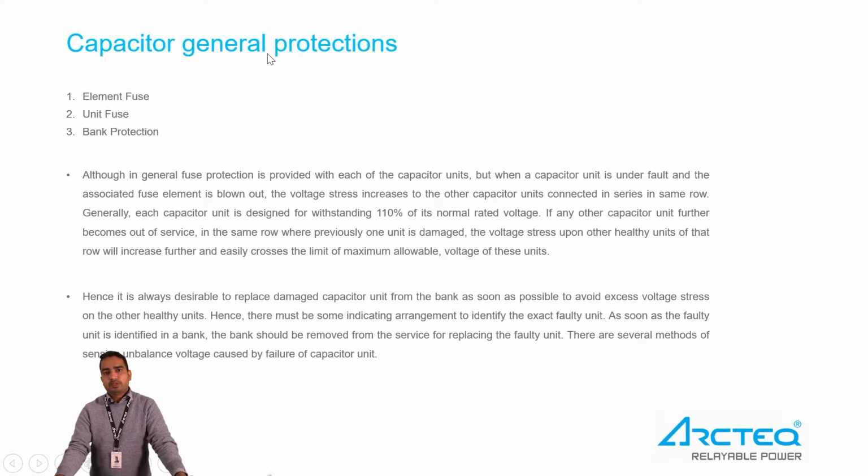So from the capacitor bank structure, we saw that each capacitor component is protected by a fuse, and then a series of the line of capacitors, those connected in parallel, is protected by a discharge resistor, and then there is the whole bank. Now what happens here is, when there is an internal fault, one of the capacitor components is isolated from the whole bank when the fuse is blown out. And this does not affect the whole capacitor bank. It stays in operation and it stays normal.